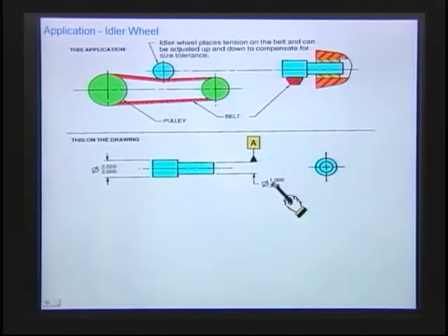Because the size here, the ovality here, it contacts on the high points. Now remember, if I was ever worried about the ovality, as in the bearing that I had before, the idler shaft, you could always put a roundness or a cylindricity on it to control it. But because ovality, just by putting a position on it, wouldn't be controlled, you would have to have some kind of tolerance on that.